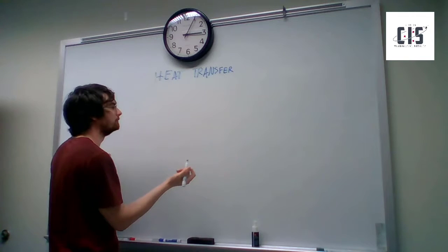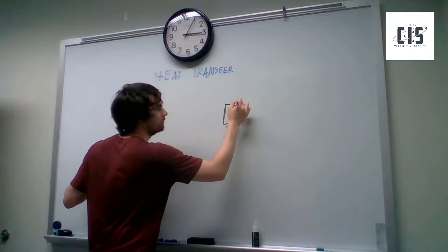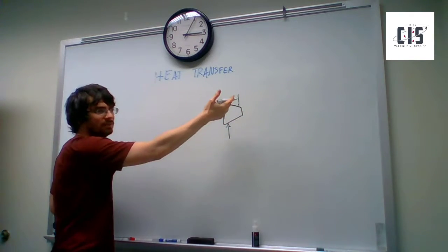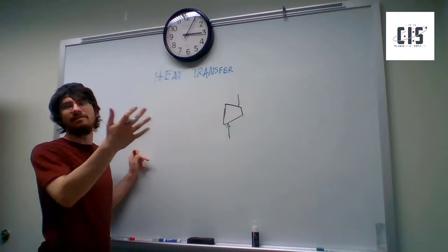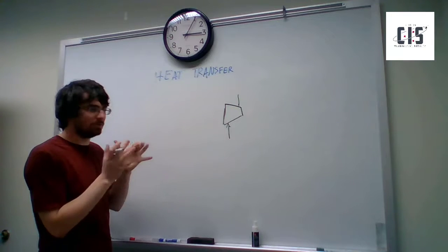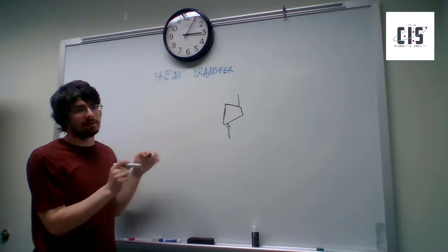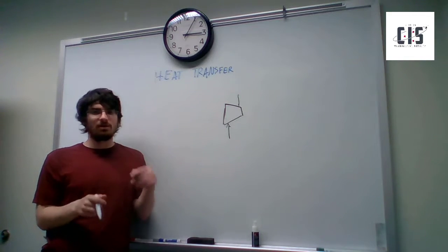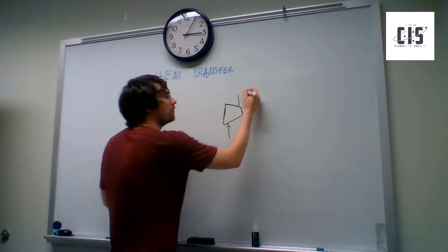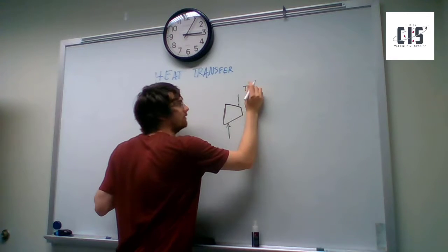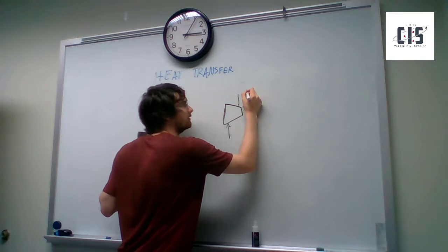So you've got a compressor. It's just one small compressor. It takes gas in, pressurizes it. But in this process, it also tends to add some heat to the gas. When you compress something real fast, it tends to warm up also. If you do it really slowly, you can do it without the temperature rising too much, and that is more efficient. But it takes a lot more time, and it's just not really worth it. And that's why you hear a little buzzing noise. Go up close to your refrigerator. Yeah, it's the compressor.